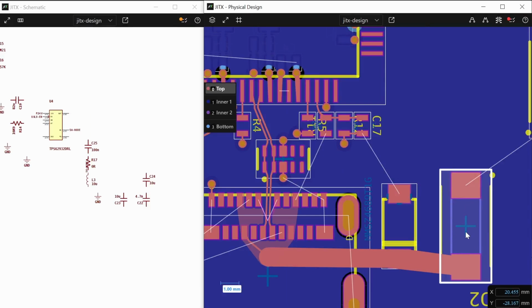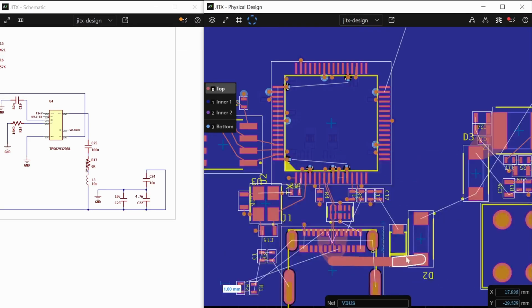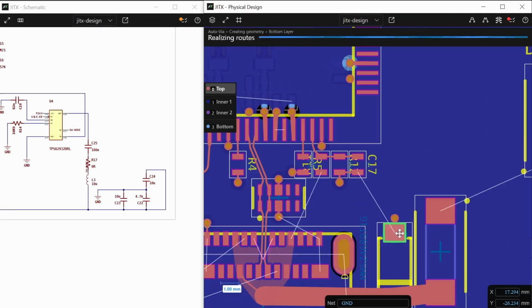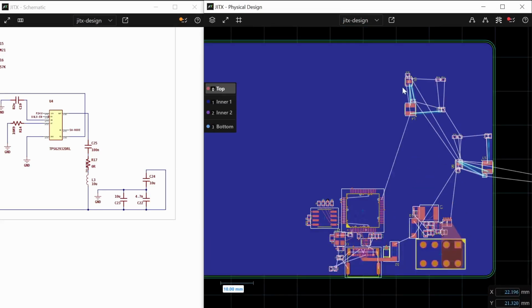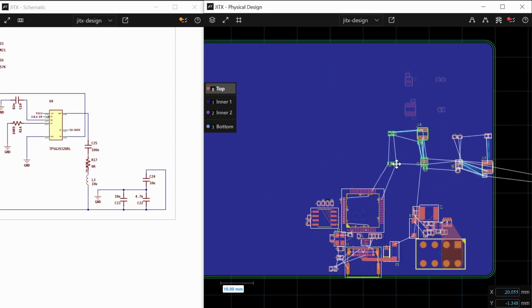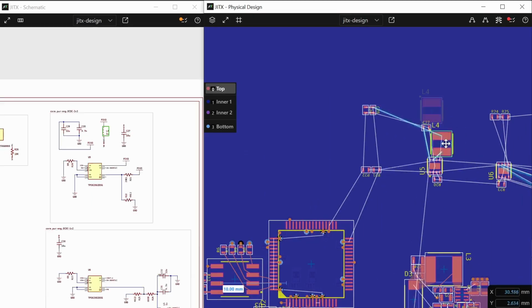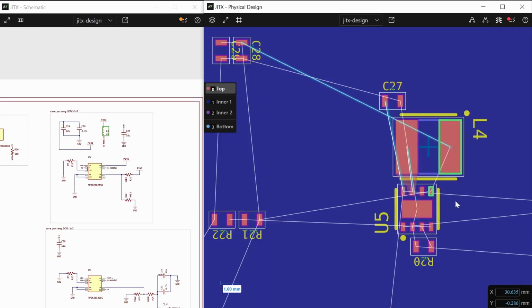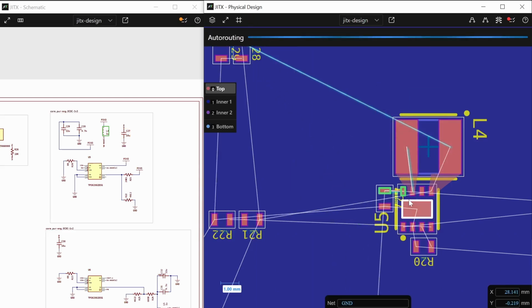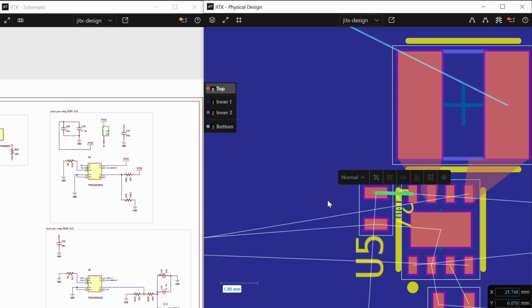And you still have this sort of alive aspect to your layout where we can figure out what our ideal configurations are. Okay, speaking of, let's get these other regulators figured out. I'll bring my inductor in here, C to create a region, C to create a region. Input capacitor, you can identify with the short trace there. You could route it, and you could also press C. So as a backup, nothing's stopping you from creating additional pours.